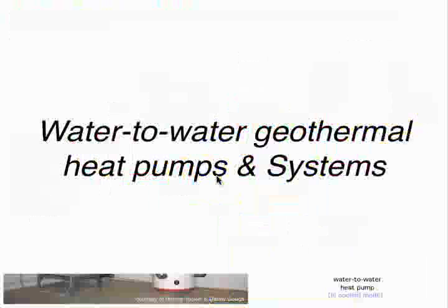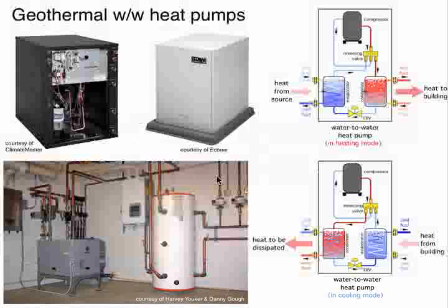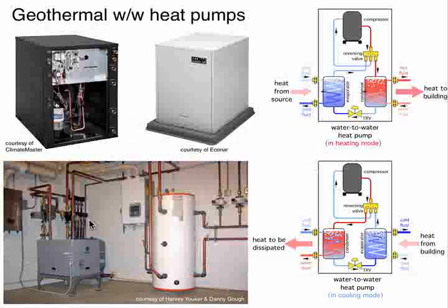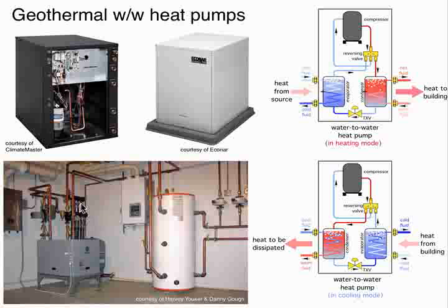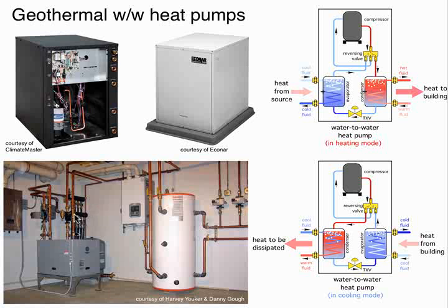Let's jump over to water-to-water geothermal systems. Again, I won't spend much time on this. The standard refrigeration cycle. We have a very nice, neat installation here. This is a WaterFurnace unit. We're going to take a look at this manifolded earth loop configuration later. But you can see that's piped over to a Caleffi Thermocon buffer tank. And then from there, we go off to multiple circulator-based zones in the system.